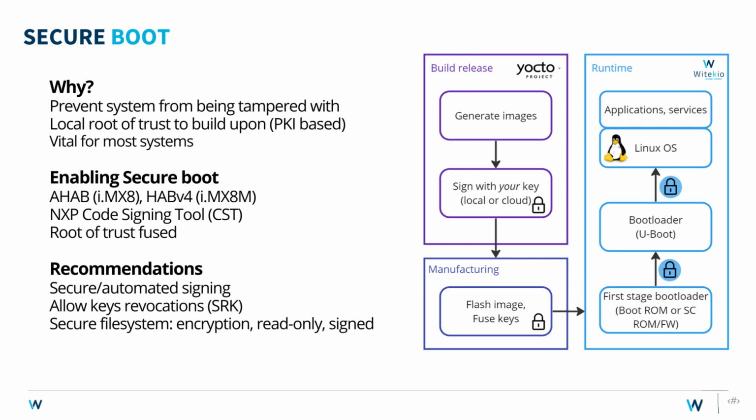from your build process, the additional step here is that you're going to sign your image with this key once they're generated. Typically, it'll provide 4. The recommendation is you keep 1. The 3 others you put somewhere very safe, because you only have these 4, and once they are fused, if the 4 of them are gone or lost, essentially your device is bricked. So out of those 4, you want to use 1, secure the 3 others.